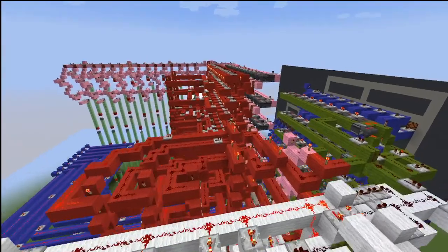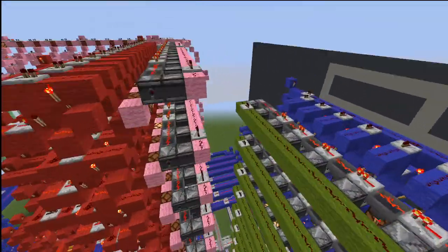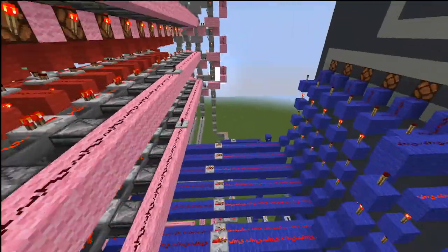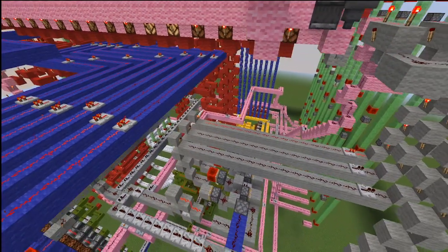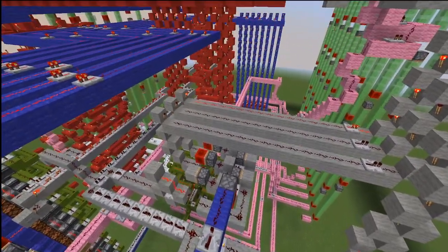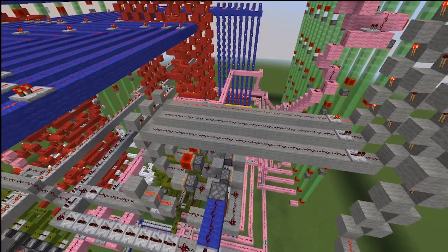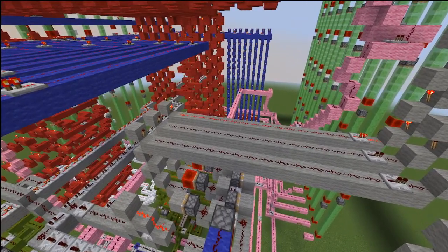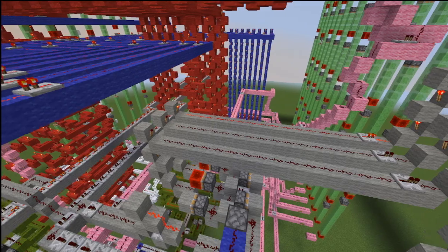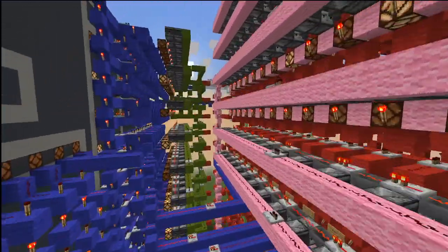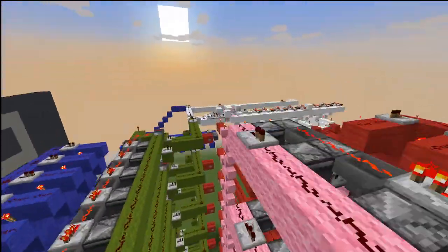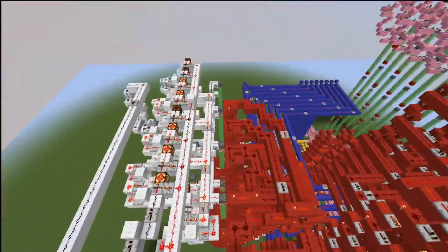And right about now, it should have already updated the instruction set, and it should be incrementing the program counter, which it just did. So now the program counter is at 4. And after this clock pulse, it's going to write the data from prom line 7 to the address and data bus up here. So we'll get to watch that happen.